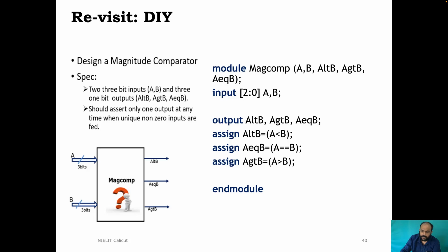If you look at it, the functionality here is represented in just 3 lines. Now compare how much easier this HDL way of design entry is compared to an equivalent schematic entry. Ultimately, whether you enter it as a schematic or as HDL, the synthesis tool converts it into a structural equivalent. So from a designer's perspective, design entry using HDL is a breeze compared to its schematic counterpart. That's a point I wanted to impress upon you, to clearly tell you the motivation for learning hardware description language.